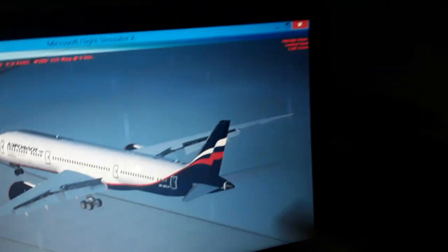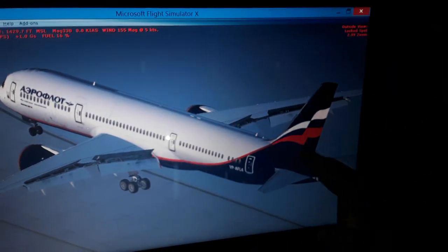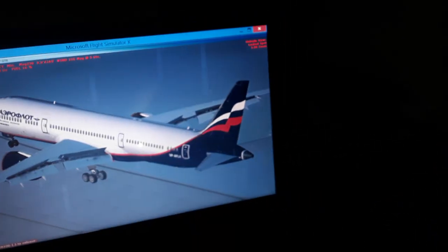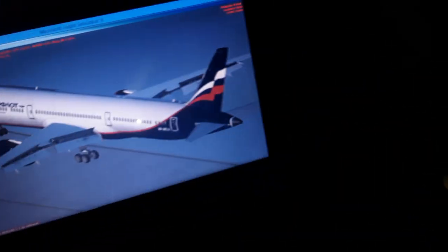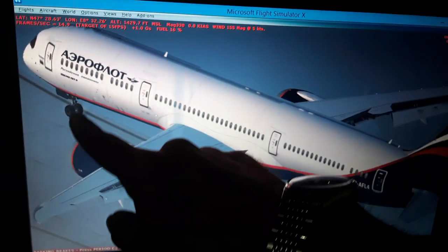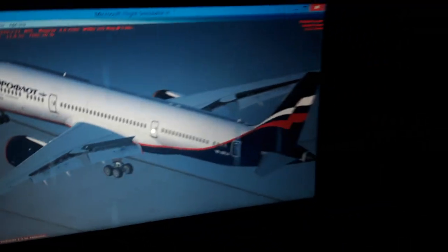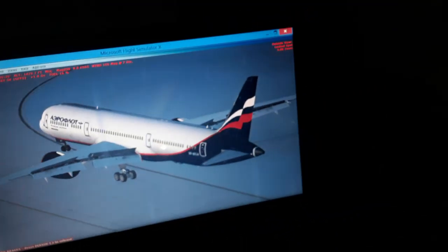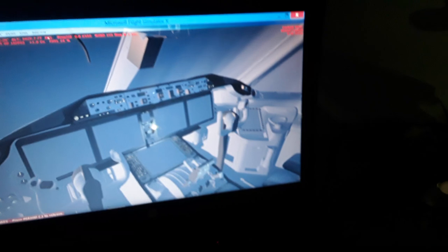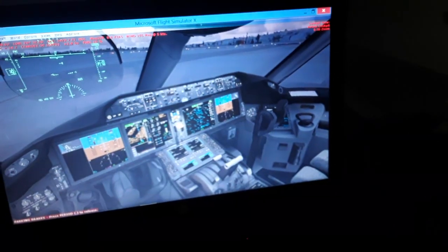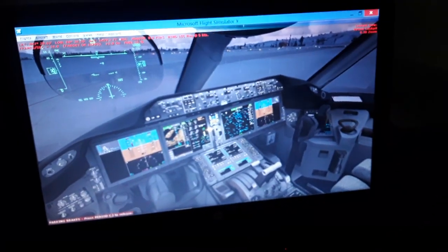Also, when we increase the airspeed above 80 knots or 144 kilometers an hour, the rudder becomes more aerodynamically effective, and the computer will limit automatically and lock the deflection of the forward nozzle to 0 degrees, or half a degree. So this is how the rudder pedals control the rudder and the nozzle.